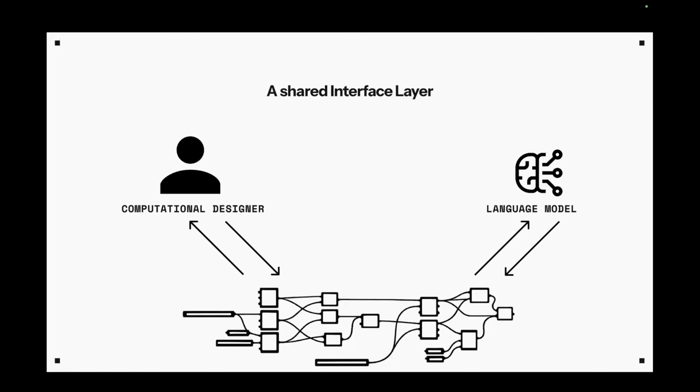Whereas with Raven, it's very different. You get a workflow, right? So it's not just, hey, here's your geometry output. Instead, it's here's the logic that constructs this geometry output, and it's exposed to you, so you can see the algorithm that makes the thing, and you're also shown all of the inputs. So it's kind of an invitation: you say, hey, Raven, make something, and Raven shows you not the geometry result, but the process to achieve it, and you're invited to come in and change things. So it's like, okay, make my building, and then here's my workflow, and you can come in and say, oh, actually, I need to change the building height. I want to add an extra floor. I want to change the base shape, and all those things are super easy.